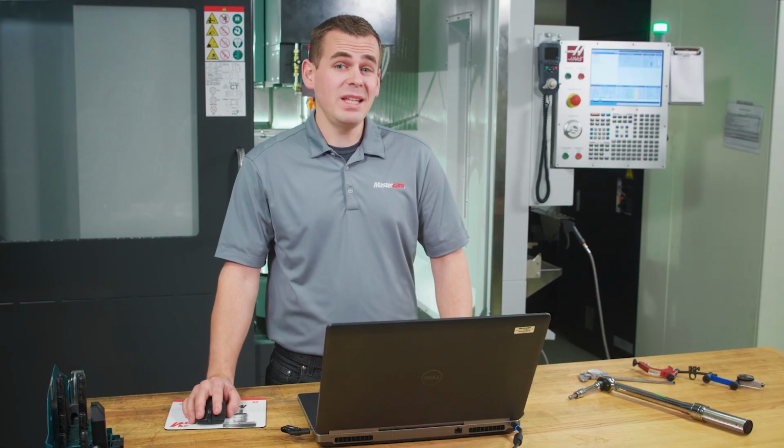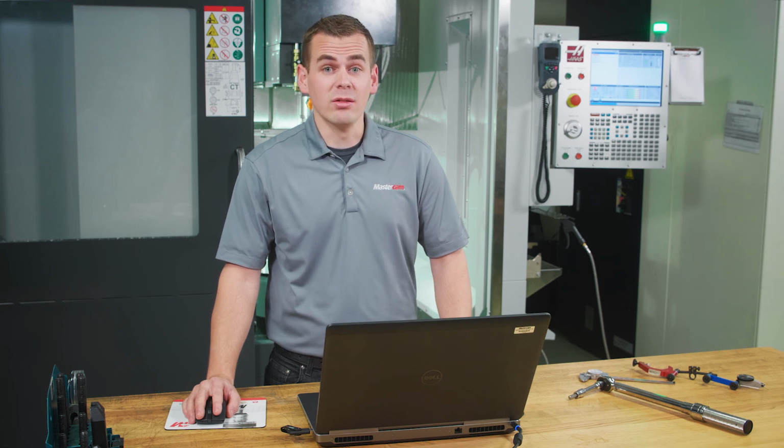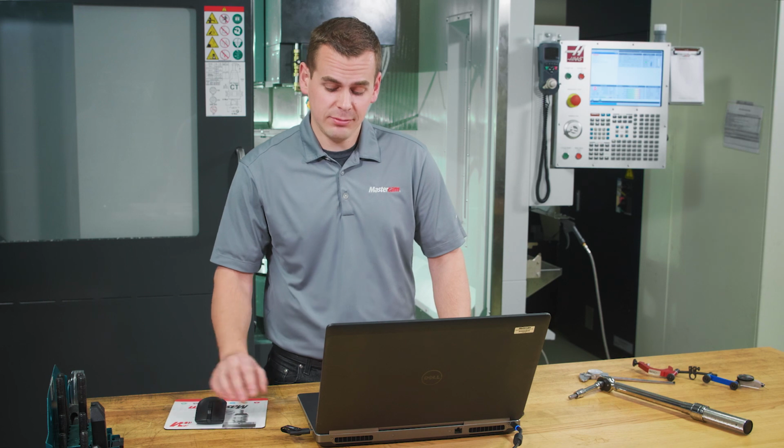We're tightening our P and corner rounding values as we move through the toolpaths, and since those values are being set in the G-code, the control will dynamically change the high-speed machining modes to match the intention of the programmer.